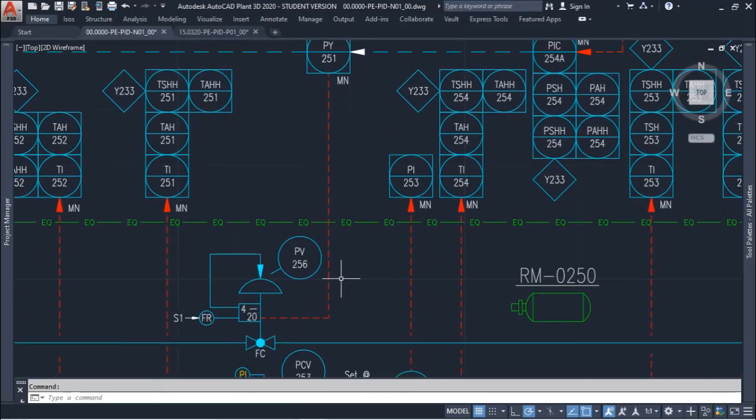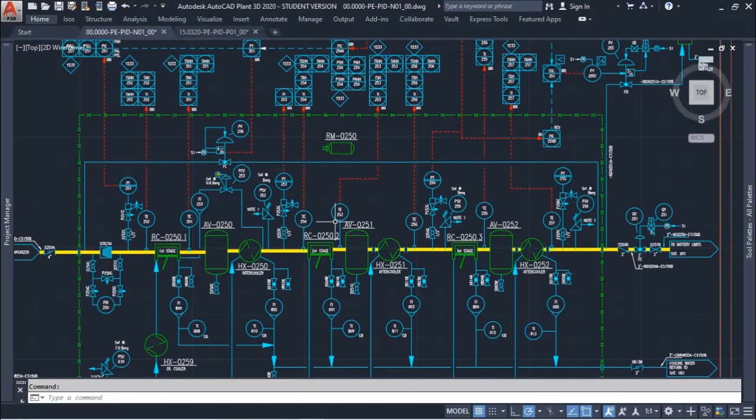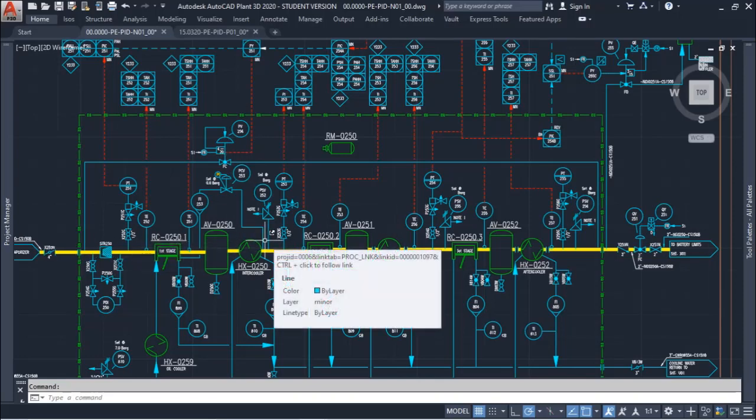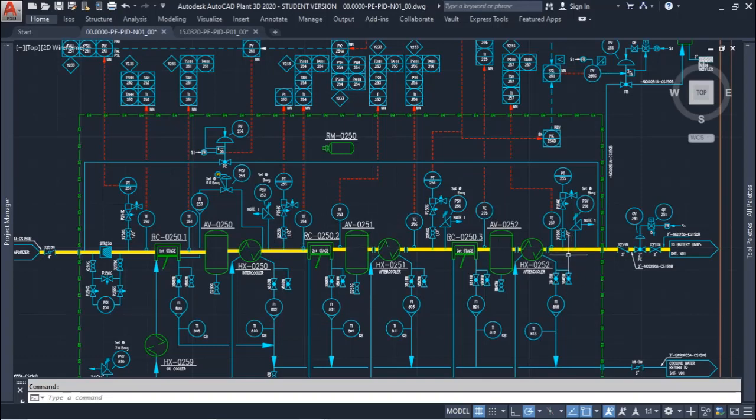And one other interesting piece of information here is that the reciprocating compressor, in this case, we start with the isolation valve closed and the recirculation valve opened, because it builds pressure too fast, and to prevent overpressurization we do that.